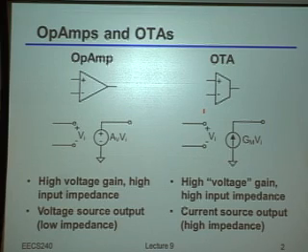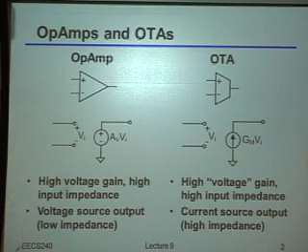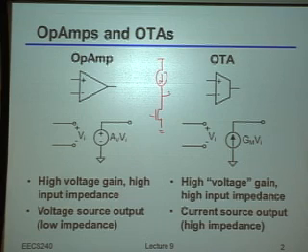Okay? The other point that I just want to briefly mention, which should hopefully be obvious, is if you went and you built pretty much any straightforward transistor amplifier that I know of, what you're really typically going to get is not an op amp. You're actually going to get an OTA. Right? Because if you think about it, if I just took this simple common source amplifier here, I take an input, I go through a GM, and I dump it into hopefully a high output impedance to get to the output. In other words, indeed, this is really an OTA and not an op amp.